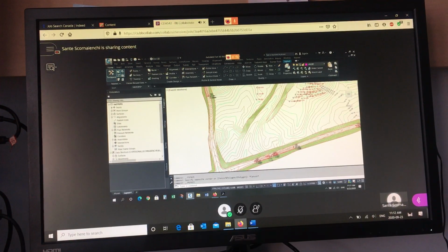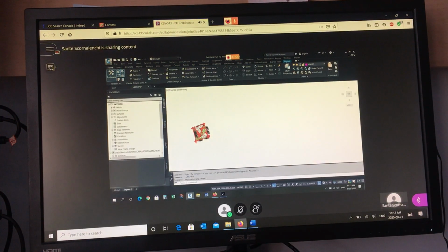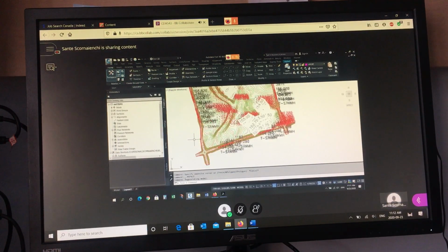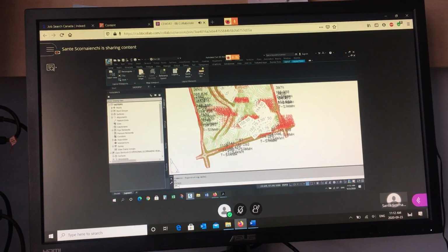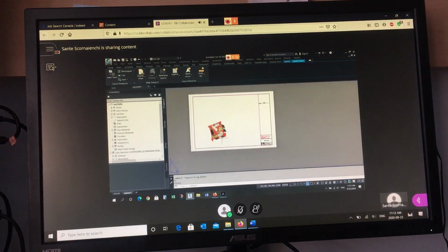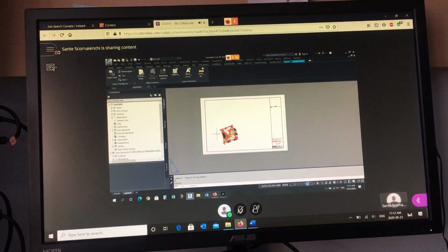If you're zoomed in and you double click here, oh, it's paper space. How do I get back out? Well, you can't zoom out. Now you're stuck in the window. So this happens to some students. Instead of double clicking outside the frame, which is not in the field of view right now, you can type in PS for paper space. Then that other icon comes out, and now you can zoom out of the frame. But now you screwed up your scale. So you gotta fix this again.